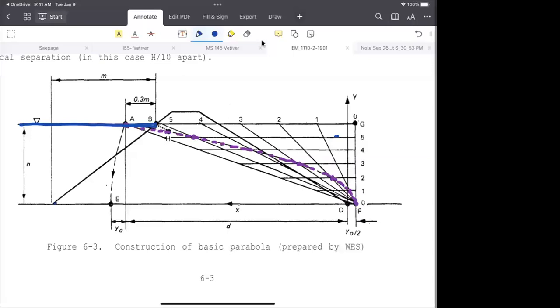So this surface is our equipotential line, right? This is the first drop. So our flow line should intersect at a right angle, perpendicular. So from here, first we have a perpendicular line, and then that perpendicular line should have a smooth transition to the flow line.